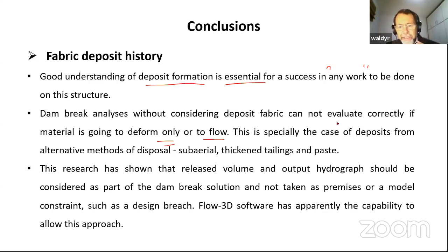This is especially the case of deposits from alternative disposal methods: subaerial, thickened tailings, and paste. Remember, the material is going to be discharged maybe with a high solids content, and that is going to be higher and higher as the material desiccates.